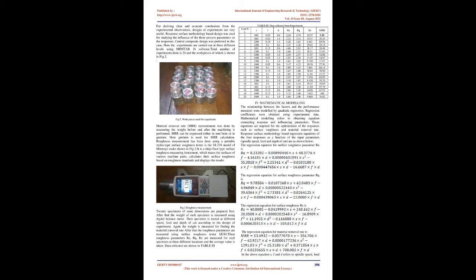[17] used genetic algorithm for optimizing surface roughness and material removal rate in turning of Inconel 718. Mathematical modeling was done to show the influence of cutting speed, feed, and depth of cut on surface roughness and material removal rate. K. Vijayakumar et al. [18] applied ant colony algorithm for solving multi-pass turning optimization problems. The machining parameters were determined by minimizing the unit production cost, subject to various practical machining constraints.